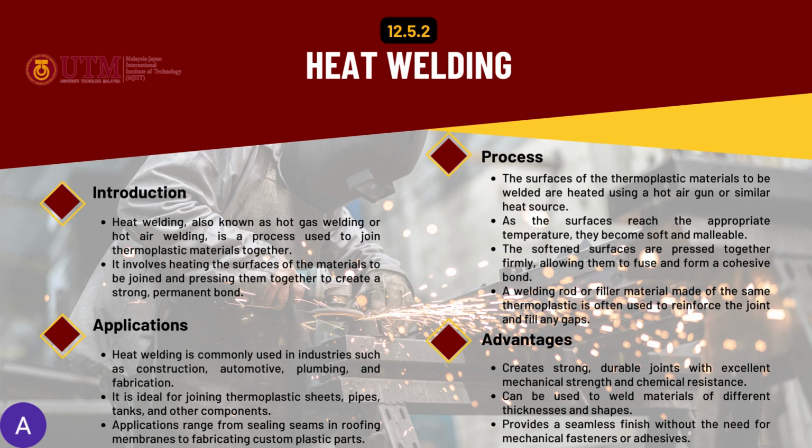And then the softened surfaces are pressed together firmly, allowing them to fuse and form a cohesive bond. And then the welding rod or filler material, made of the same thermoplastic, is used to reinforce the joint and fill any gaps.